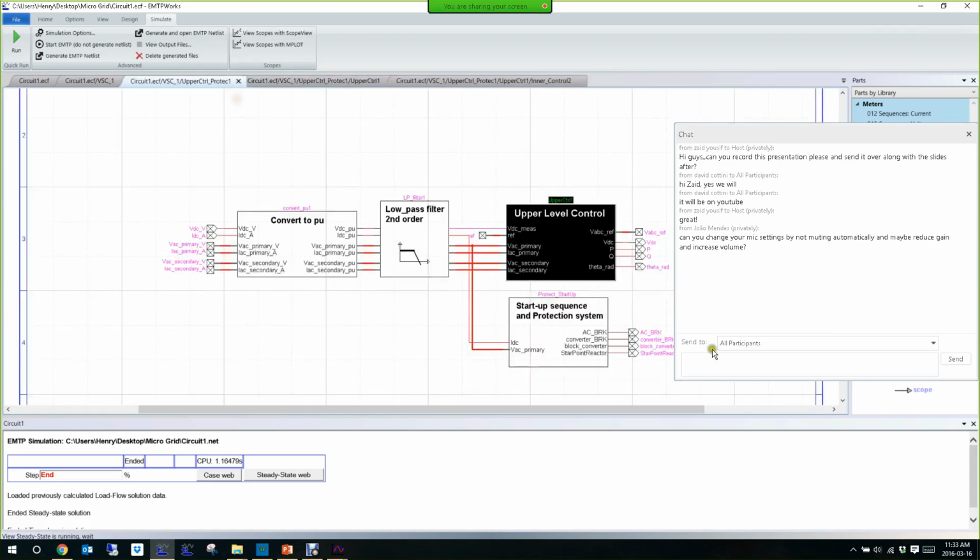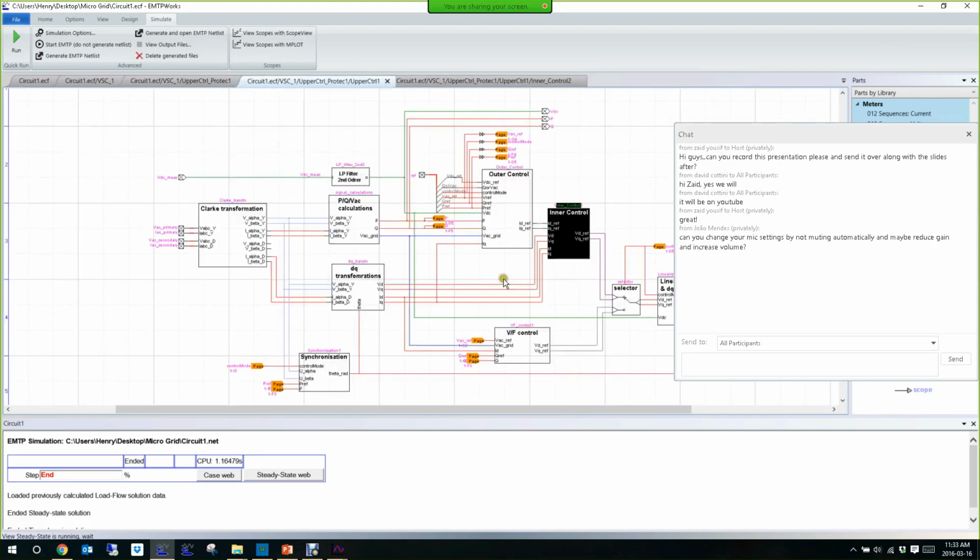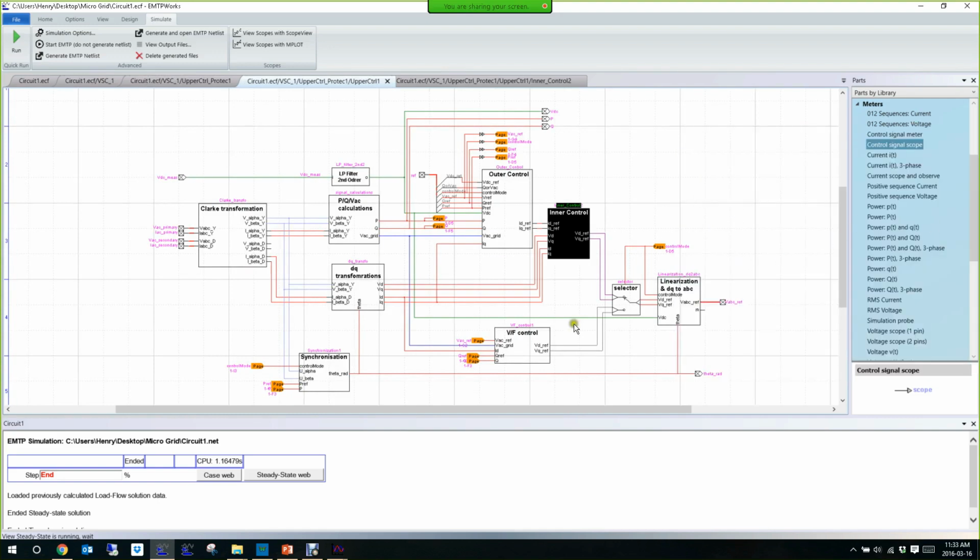So why is that? If you put an equation to all that, you have a non-linear system where in the same equation you have the voltage and the square of the voltage. So it's too hard to do a control for that. So what we do is we do the control in two steps. Like that you have only linear systems, one for the current reference and then one for the voltage reference. That's the reason: when we put the equations of everything together, we have a non-linear system.